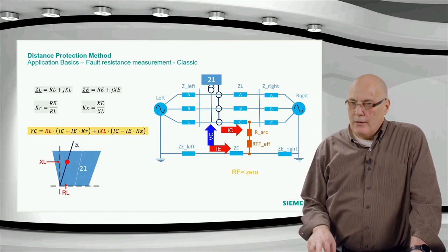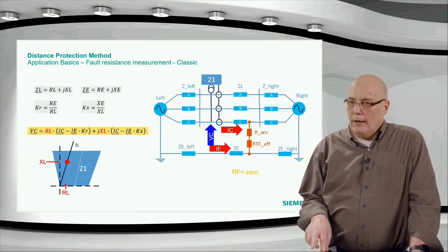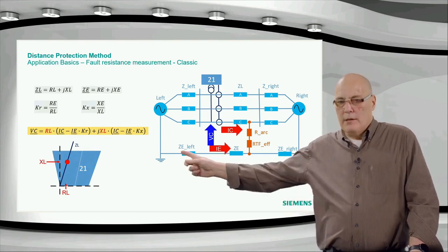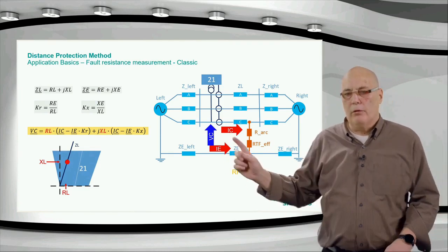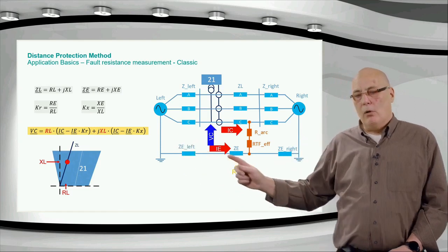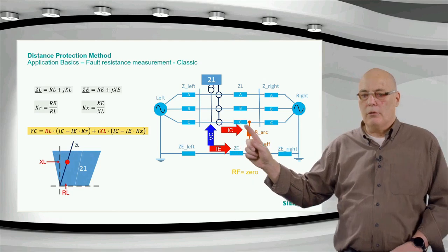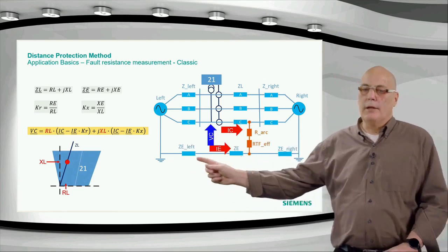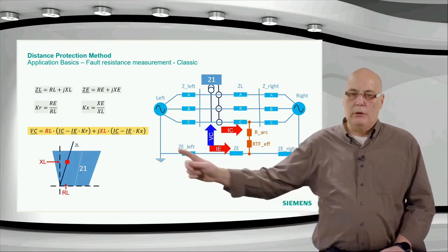And then it is RL times IE, but no, it's not. It's IE times ZE, and you can see the minus sign there because you must remember the polarity. This is something you must be very careful of, because this loop is going in this clockwise direction and the IE is in the opposite direction. So if we take the loop and rotate with the finger, going this way around, you can see the IE is pointing against the loop direction. That's why we need a minus sign there.